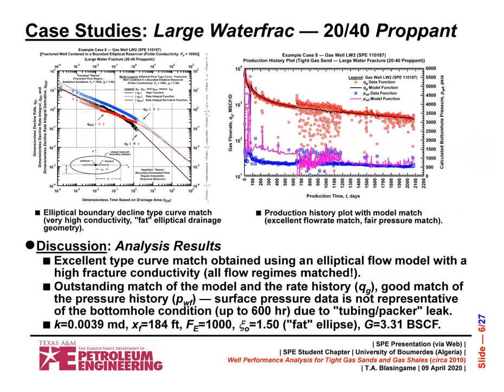The next was a large stimulation treatment, and this time what you'll notice is that the rates are significantly higher over in this region, and then there's some sort of a situation here. We assumed this had to do with liquid loading. Probably the tubing was not being unloaded properly, and this affected both the rates and the pressures, and then somehow they resolved that and it came back on trend. So looking at the raw data, most people see this and go, oh, something must be wrong with the data. No, it was something to do with the operational approach used in the field.